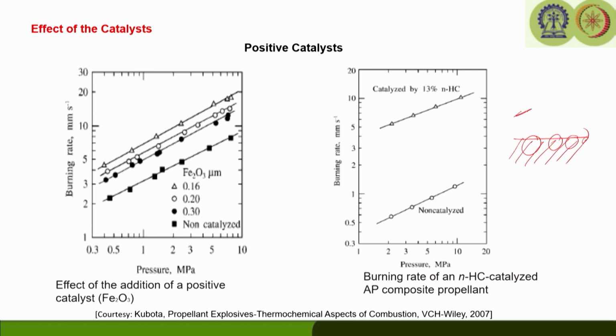So, we have said that the three flames remain at the same plane we have considered, and this is called the standoff distance. The heat feedback coming from the gas phase to the condensed phase is going to influence the burn rate of the propellant. So, at the burning surface, how the heat feedback is coming is going to be very important.